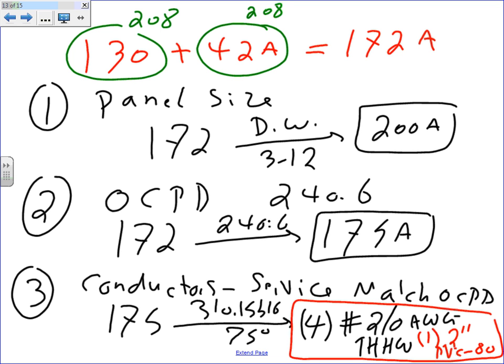No. So what would you do? You have to convert them with the voltage ratio. That's why I picked this example, because the receptacles and the lights and everything else were at 208, 120. It's easy to compare them. But had these welders been 130 amps at 480, and this load is coming from 208, I have to do the conversion where you take the 208 divided by 480 and then multiply it by this number. So it lowers it, because it will be seen as lower amps at higher voltage.